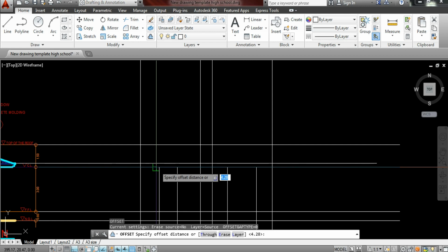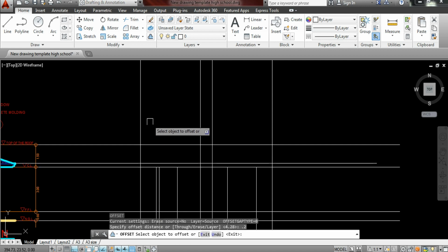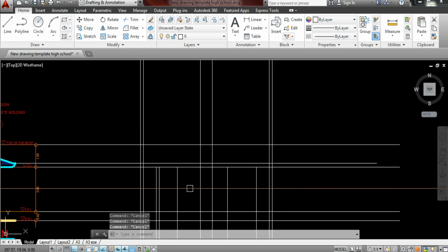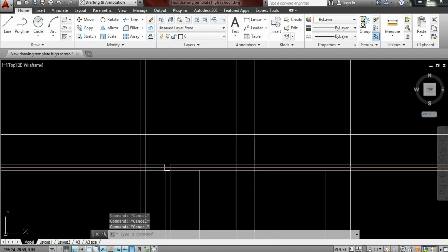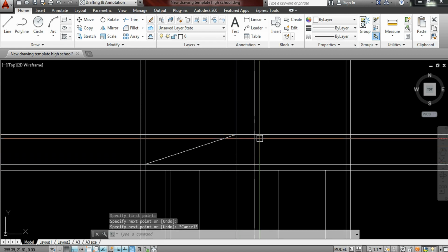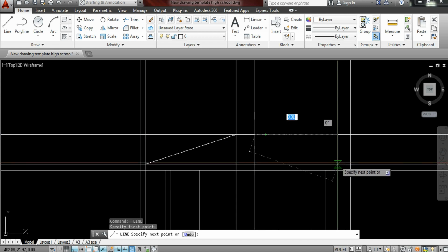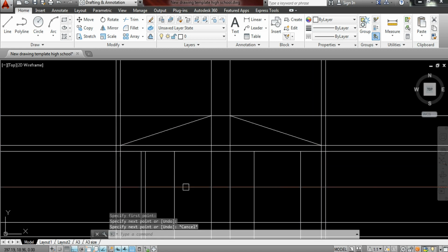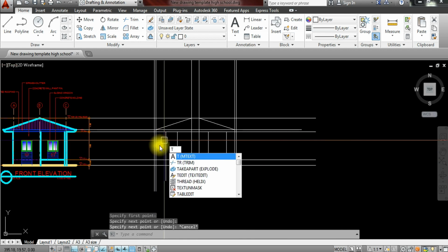Also, not to forget the distance of this edge of the gutter. Although we will copy the gutter later, it's better if it's already set. So, line from this edge to the upper part of the roofing, and then to the opposite side of the roof. Then we trim what's not needed.